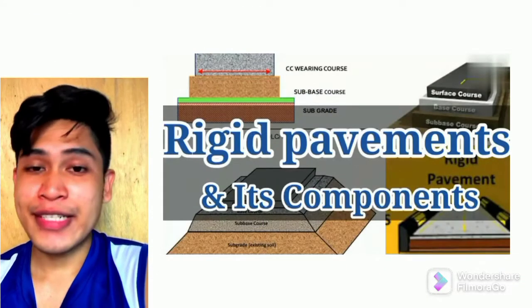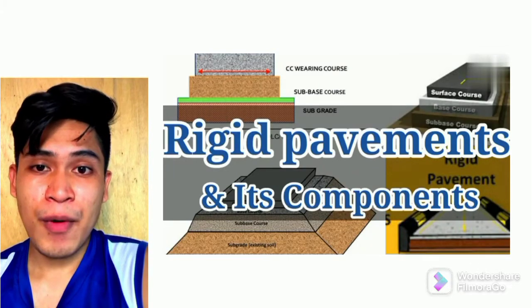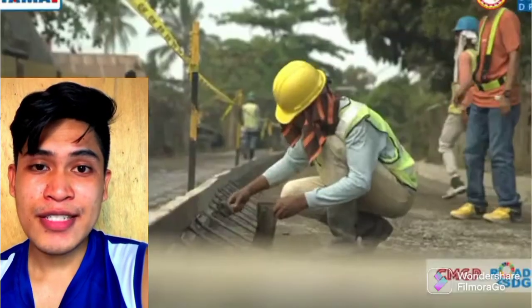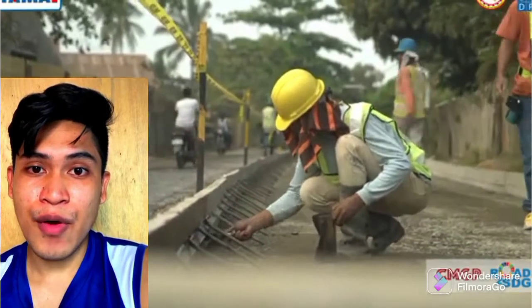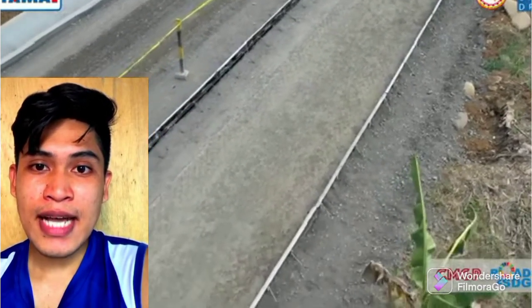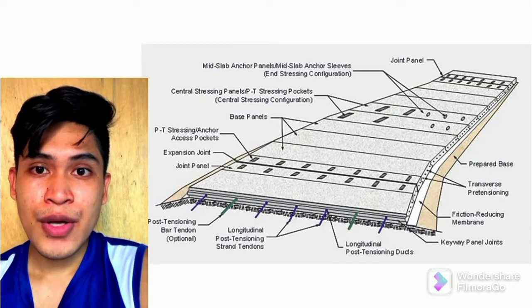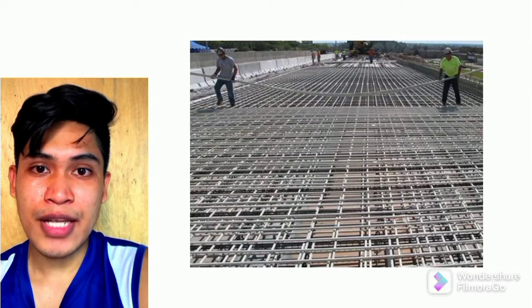Now, let's talk about rigid paving. This consists of a reinforced or unreinforced in situ concrete slab placed over a thin granular base course. The inflexibility and strength of rigid pavements enable the loads and pressures to be dispersed over a wide area of the subgrade to reduce the potential impact.